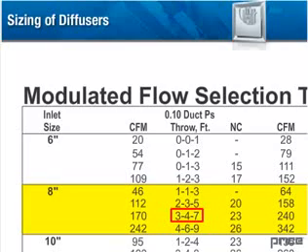Refer to the Air Distribution Guide in the Price Air Distribution Products catalog for more information on throw selection. Upon selection of the appropriate diffuser size, note the lowest air volume cataloged under the duct pressure column. This is the minimum limit of the diffuser at the listed static pressure. Assure that throw, noise, and air volume meet the required specifications.